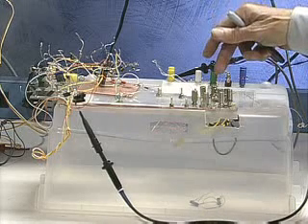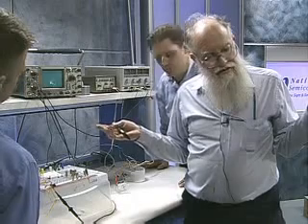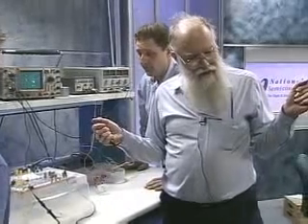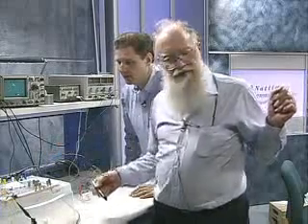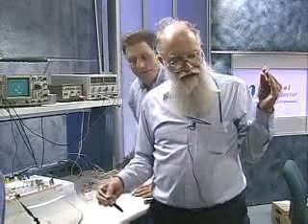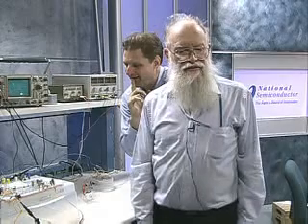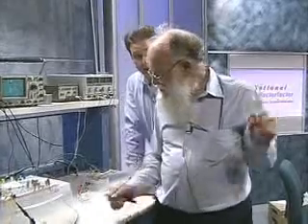0.1% 1 milliohm resistor. Why do people need a milliohm? The main point is, if you're trying to measure 80 amperes, 1 milliohm is lousy. Lots of watts. You need 0.1 milliohms to measure resistors. How do you measure a 0.1 milliohm resistor compared to this milliohm resistor? So we do milliohm and sub-milliohm resistor technology to help people measure 80 amperes. I don't approve of 80 amperes to run any circuit on, but if you have to, you can do that. I did an ECL test rack once, did 2,000 amperes.